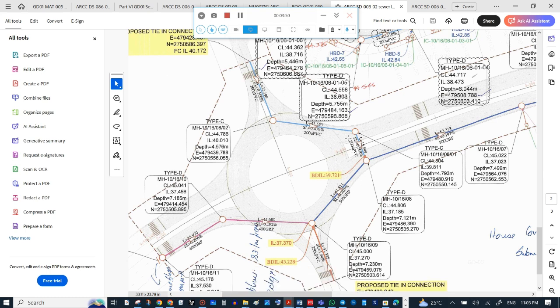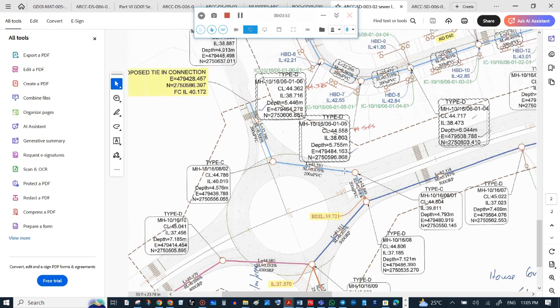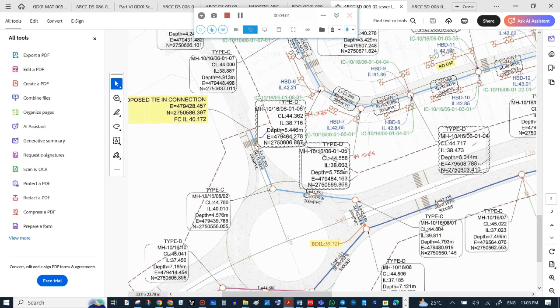Here also 200 UPVC is connected. Why is its depth 250 mm instead of 200, or why is it there? Because of the flow, calculated flow as per the design, which we will discuss when we discuss the flow velocities. So anyway, we have reached manhole drawings. So we will discuss the type of manhole again, and also the sectional details of the manhole.